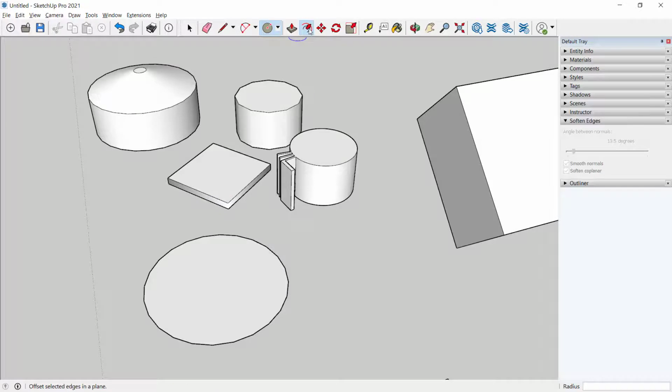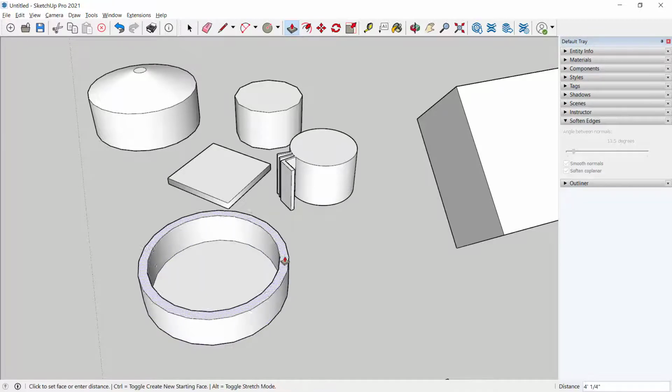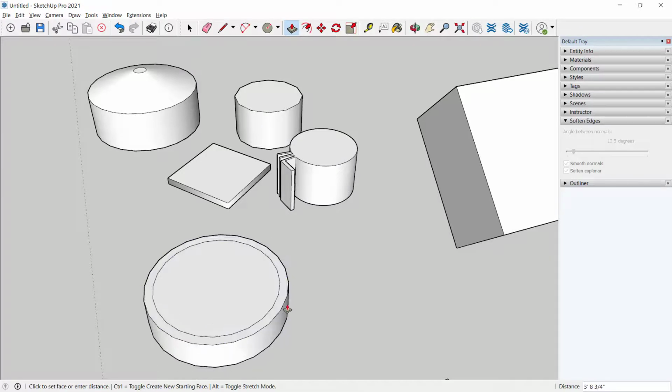And with the Offset tool, it works similar to push-pull in that it recognizes a surface. You click once to define where the offset is going. You can also type in a dimension. So for example, if I just want it 12 inches and in this direction, once it's going in the direction I want, just type in 12 and it will offset it. And I can push-pull up or down the piece. And the other interior piece I can do separately.